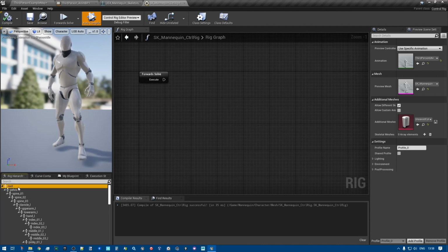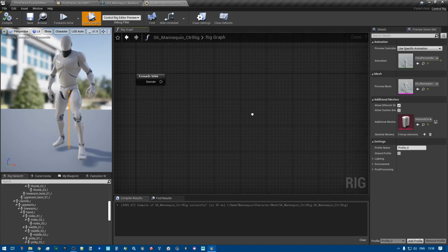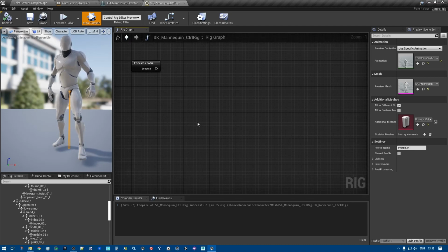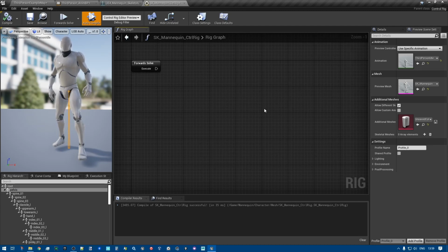The control rig says, I expect the bone skeleton, root, pelvis, head to work, but it's not hard linked with the skeleton asset. So for example, if you make a control rig for some complex IK for one skeleton, and you want to use it for another skeleton asset, which has some of the relevant bones with the same name, you can just reuse it.